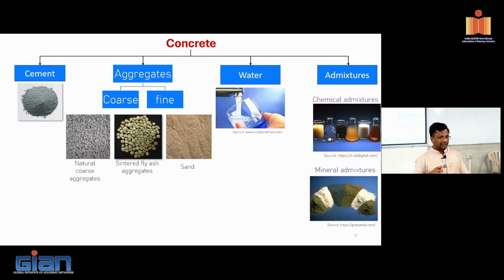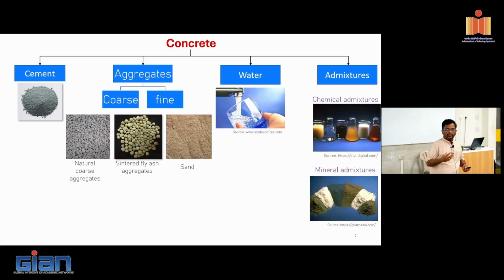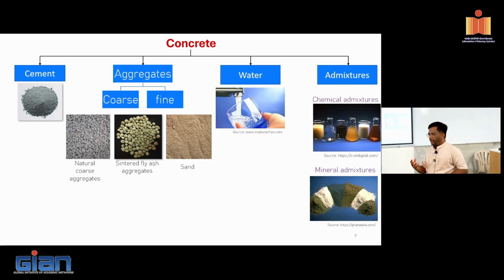Chloride should be lesser, because most of the time the RMC people or even regular construction, what we do is we try to use groundwater for making concrete, particularly in the low residential segment, G+1, G+2 kind of construction. They don't go to RMC. They make concrete on their own, right? So they use the groundwater, tap water. In the tap water, if you don't do the testing properly, what will happen? The soluble chlorides are going to be very high. And the moment you put chlorides in the concrete, which is dispersed through the entire medium, that's it. Your corrosion durability is compromised, right?